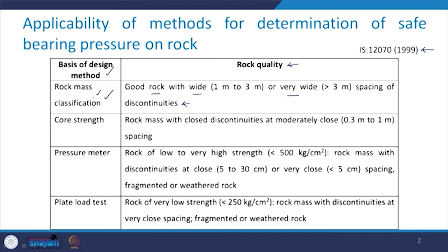When I say wide or very wide spacing of the discontinuity, as far as wide discontinuity is concerned, it may vary between 1 meter to 3 meter, and in case the spacing of the discontinuities is more than 3 meter, they fall under the category of very wide.